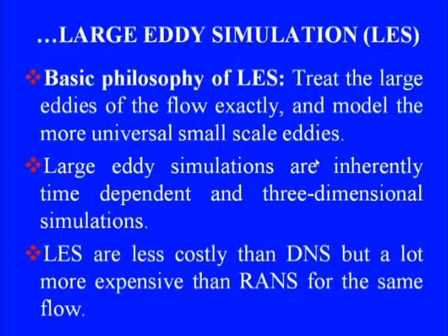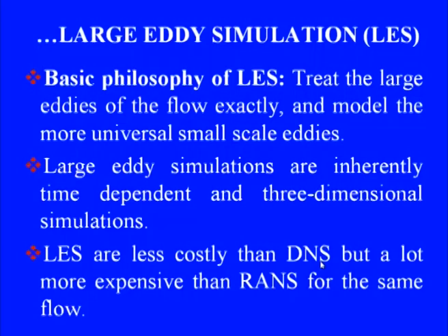Large eddy simulations are time dependent ones, and as a consequence, they are more costly than RANS simulations, but they are much less costly than DNS, because in DNS we were required to resolve all these scales, small scales as well as large scales. So, our grid size and time steps were dictated by the smallest eddies, that is the ones which have size of Kolmogorov length scale. But in LES we are not going to resolve up to that scale, we will rather stop in the middle, we will just resolve the large eddies.